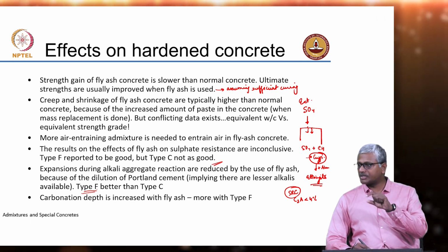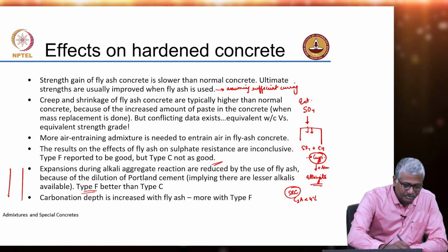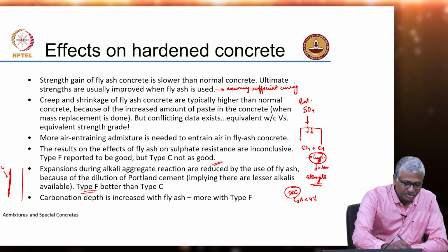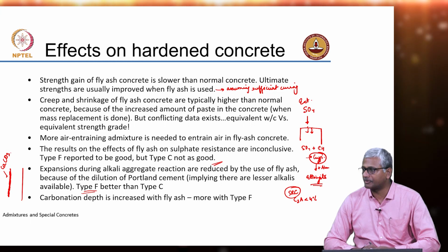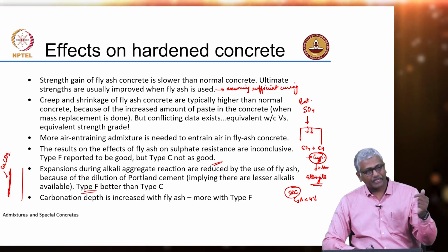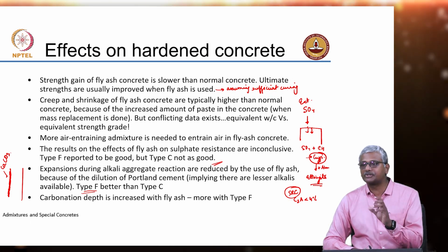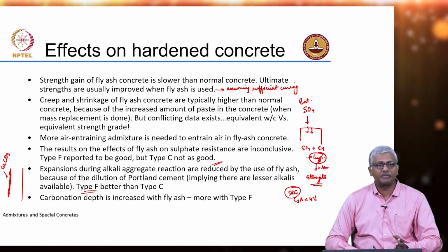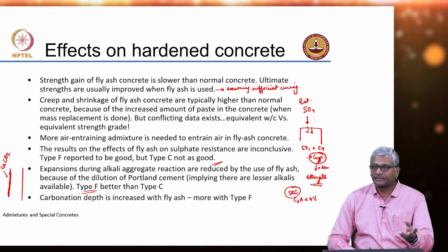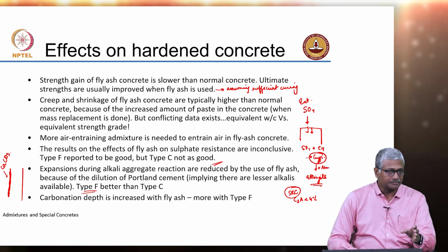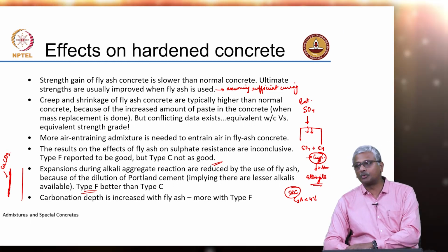In plain Portland cement, the reaction of carbon dioxide with the surface lime or surface calcium hydroxide leads to almost like a coating forming on the surface. You will have a coating of calcium carbonate formed on the surface because of the reaction of carbon dioxide with the external calcium hydroxide present in the cement paste. And this coating forms almost an impermeable barrier, and your CO2 is not able to penetrate easily. Okay. So, in other words, carbonation in plain cement concrete leads to densification of the surface, whereas carbonation of blended cement concrete does not result in such densification, it leads to more coarsening of the porosity. So, all blended cement systems will generally tend to perform poorer as compared to plain Portland cement system when it comes to penetration of CO2 into the concrete.